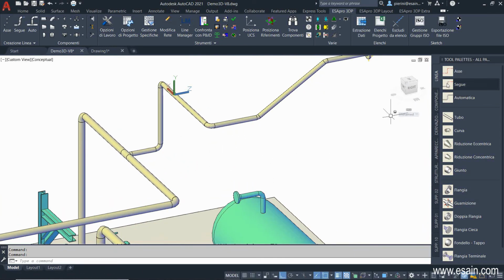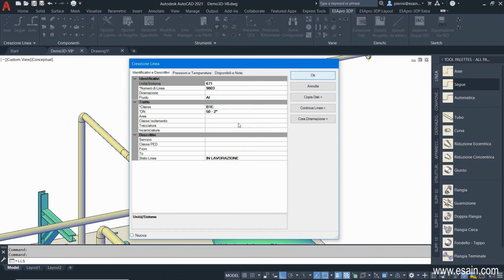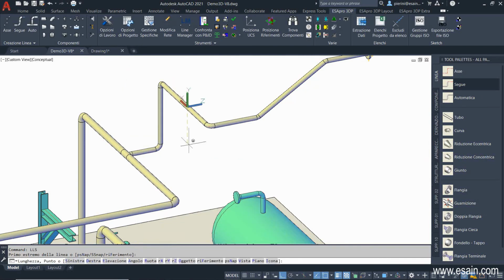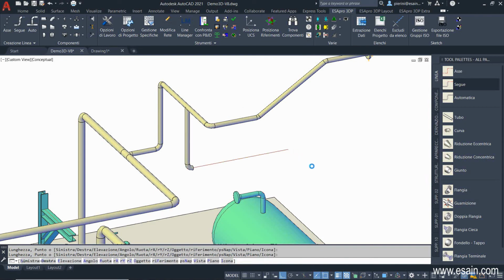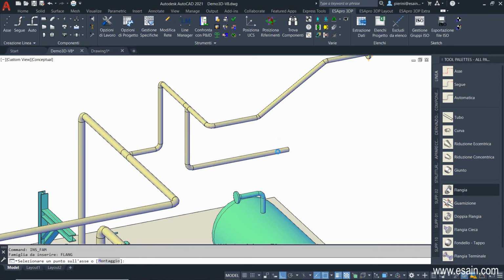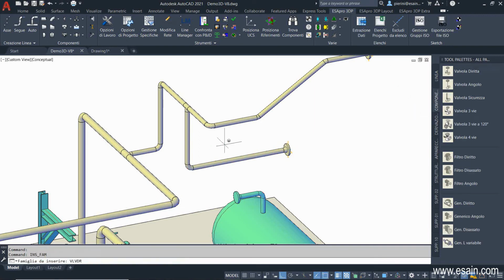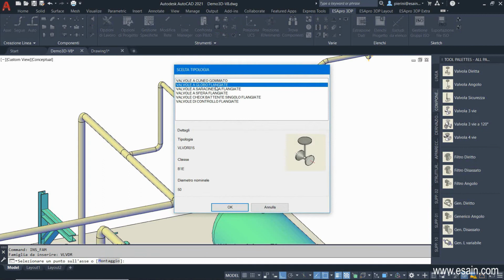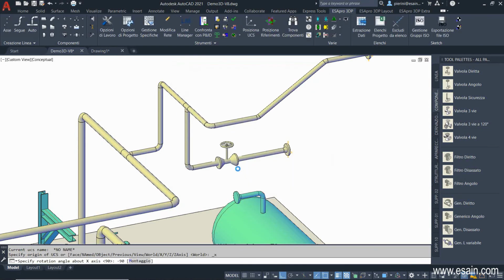Until now, we've modified the geometry, but let's see what happens when we change the technical characteristics of a pipeline. We draw a 2-inch line, which starts from an existing pipe, and then an equal T is inserted. To this line, we add a welding neck flange. And from the class, we pick a flange globe valve. The valve carries its own counterflanges, gaskets, and bolts. Also, these flanges are welding neck.